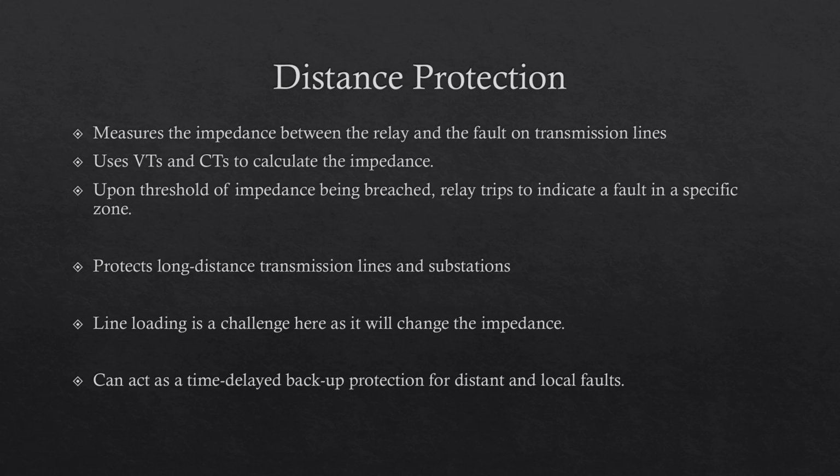So yeah, overall, each type of protection has its own uses. Some systems will use everything, every kind of protection. Some will just have their selection of maybe overcurrent and earth fault. But overall, we have overcurrent, which detects overloads and short circuits, and can be instantaneous depending on the type of fault. If it's a short circuit, we use it in distribution and motors.